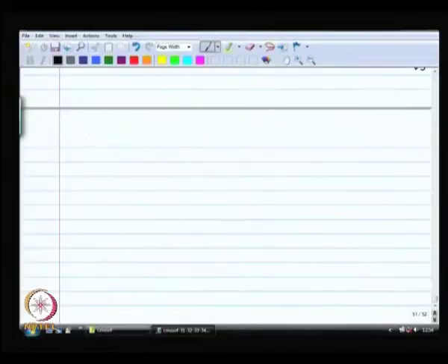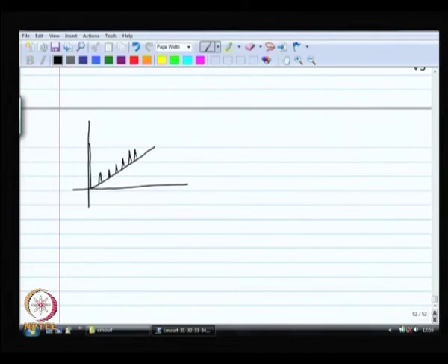And as soon as that happens, the output spectrum of the sigma delta modulator, right now the output spectrum of this first order modulator kind of looks like this. Right, these are the spurious frequencies, but as soon as you break the periodicity by making it a higher order system, you get a better rejection over here and you get a higher slope for the quantization noise.